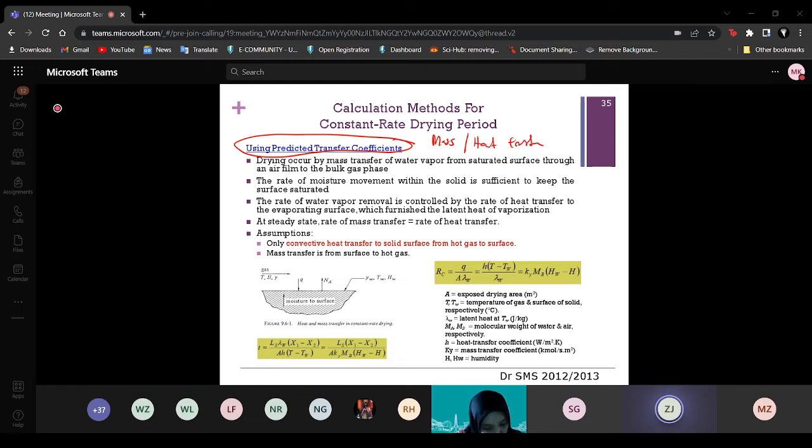All right. So because you know that in drying, you're giving heat to the wet solid, and then the moisture gets energy and then vaporizes. Okay, water is removed as vapor. So that you're going to have heat transfer. The heat gives energy, and then the mass is removed, the water is removed from the system.